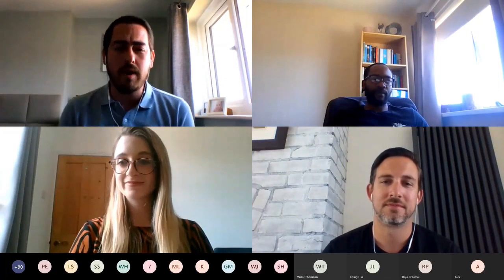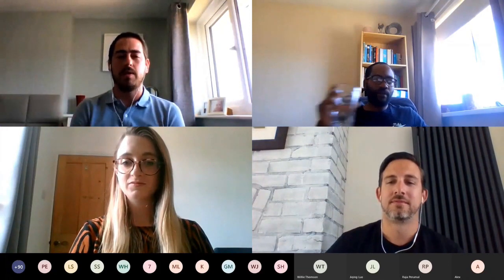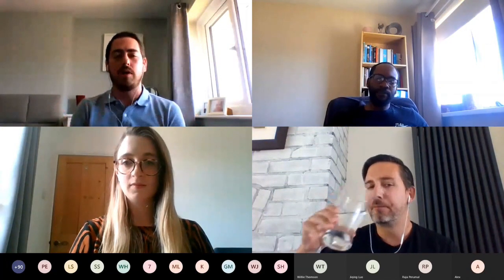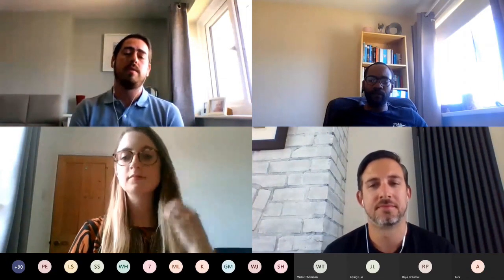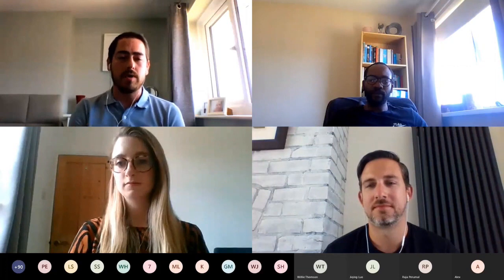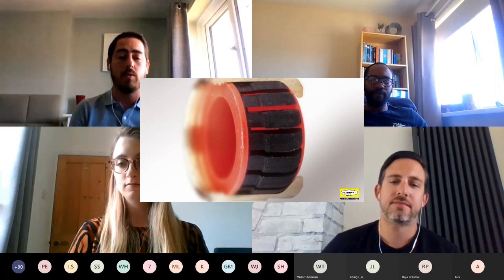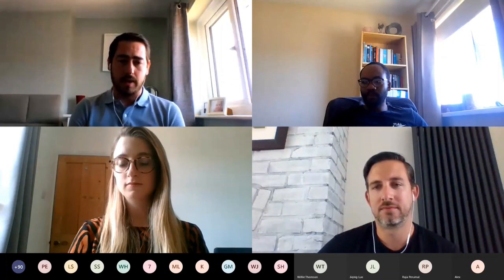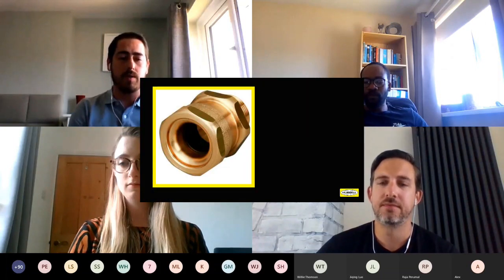Absolutely. Rather than going through the individual cable glands that we offer, I think it's easier to split it down into component form. If we think about the inner and outer sheath of a cable, each has a seal. We actually have 5 different sealing options. We'll start with the orange seal that you tend to see on the back nuts of cable glands. They're predominantly only for our armoured cable glands. We have compression seals, and they can be used for IP seals as well.